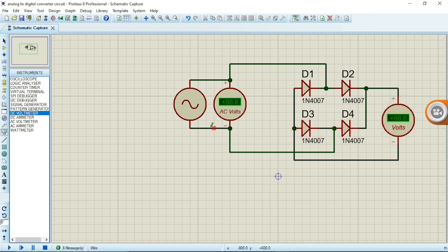You should expect voltage that is lesser than this AC voltage, and I'm going to be simulating it right here. So we have 17 points or 18 points. This is fluctuating. Yeah, it will fluctuate, and that's why I said it allows only the positive parts of the AC voltage to pass while neglecting the negative parts, and here is not fully rectified. And the next thing we are going to be doing is use a component that will stabilize this, that will make it more rectified, and that's what brings us to capacitor.